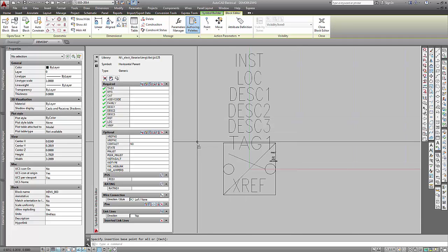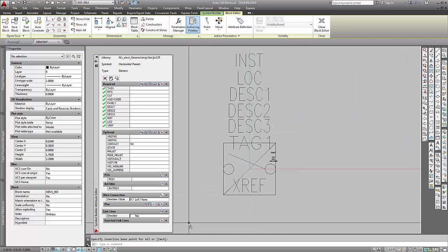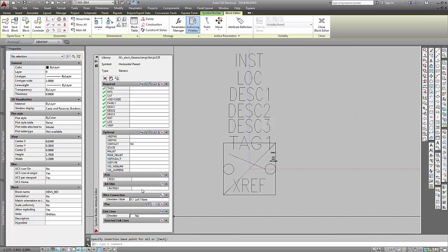It is important to note that you can create a symbol that has no attributes at all, and if you insert or edit the symbol without attributes, the editor will add the information from the catalog and the dialog box as X data. Attributes are easier to work with than the X data, especially at a later date.